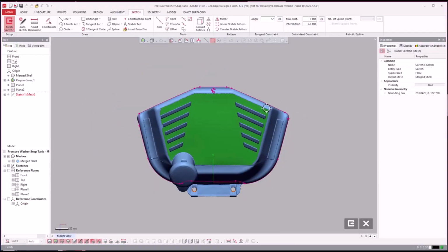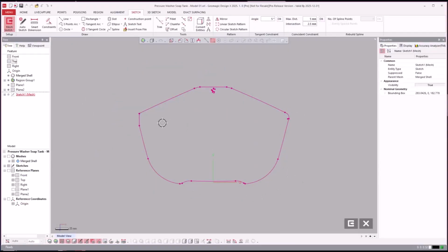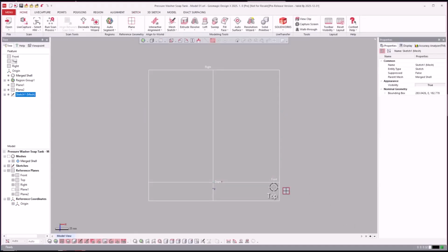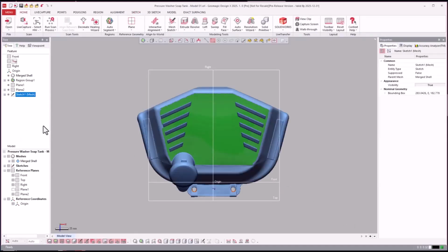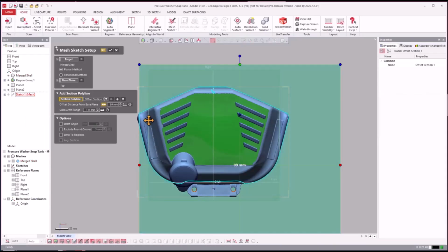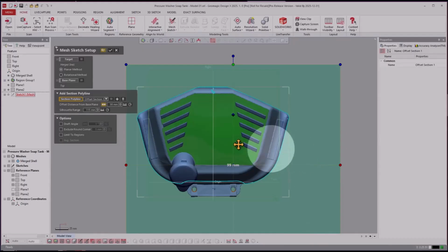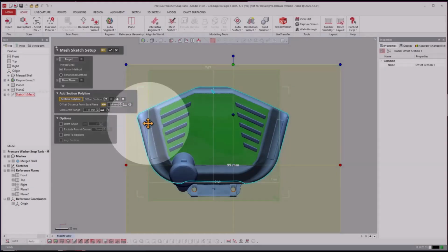It takes us inside of the mesh sketch. I can turn that off, and we can go ahead and draw our mesh sketch. Oh, and I'm noticing something going on over here. So I can accept that mesh sketch, by the way, turn my mesh on, and I can come back and hit edit mesh sketch. And you see, yep, it just happened that me moving the box around somehow moved this side in a little bit.